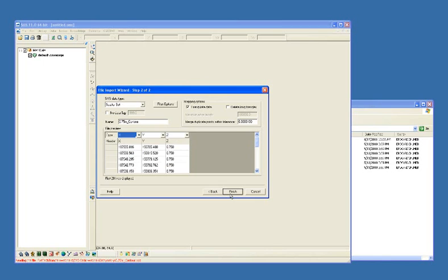So I'll just click Finish, and notice that there's an option here to triangulate the data. If you have a very large Lidar set, say, and you don't necessarily want to take up memory space for that to be triangulated, you can tell it not to. So you would just uncheck that box and it would just bring in the points, but it would not triangulate between them. But in this case, we're just going to triangulate everything as we bring it in.